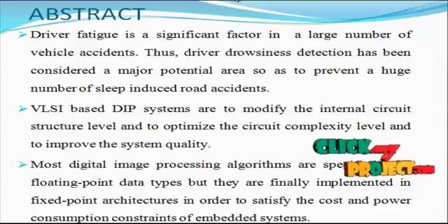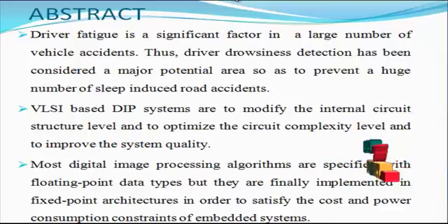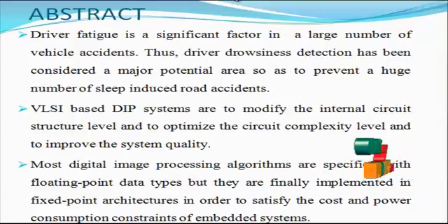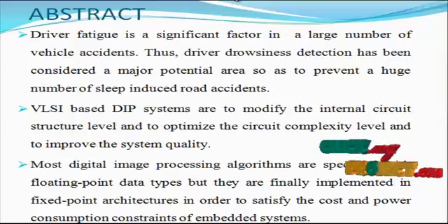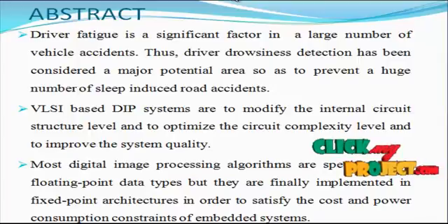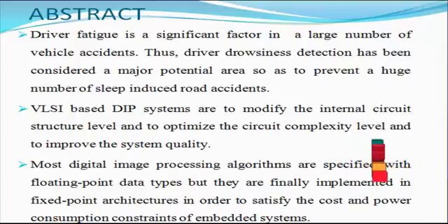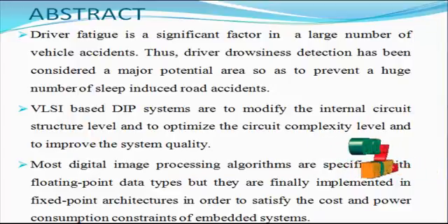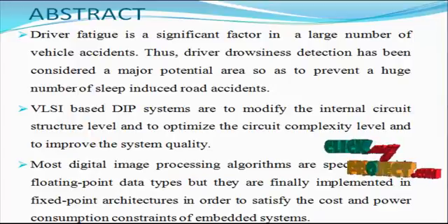These are non-intrusive ways of detecting drowsy drivers, but they are limited by the type of vehicle and driver conditions. Another set of techniques focuses on monitoring physiological characteristics of the driver such as heart rate, pulse rate and electrocardiography. Research suggests that as alertness level decreases, the ECG power and the alpha and theta bands increase, hence providing an indicator of drowsiness. Although these physiological signals yield better detection accuracy, they are not widely accepted because they are less practical.